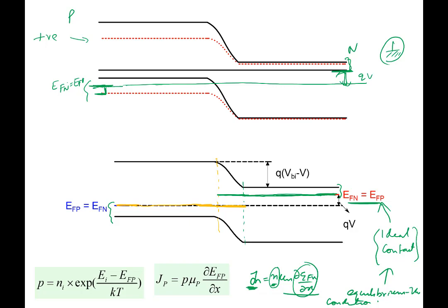Now in this, it goes like this here. It starts to decrease. And note that they have to return back. Eventually equilibrium has to be there, so they have to return back to this at the other end here. So the two, EFN and EFP, have to merge together. So look at the behavior of EFN and EFP, and understand why we are saying each one of those things. EFN is flat till here, because we look at this expression, we say n is pretty large, n equal to Nd. So it's approximately constant till this particular point. Yes, n is decreasing, but this region is also very narrow, and we keep it flat here. And then after that, the quasi-Fermi level has to reduce and eventually merge with the EFP, because equilibrium prevails at the contact here. EFN equal to EFP. Same behavior occurs at this particular point here. So this is the behavior of EFN and EFP in a PN junction, how the quasi-Fermi levels go.